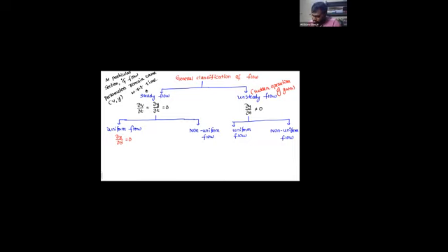And I can write in other words, if depths are the same, velocities are also going to be the same. So along the length of the channel, if the flow depth and velocity remain the same, then you are going to call it uniform flow. I have used this condition in the starting itself. Yes or no? And sir, where do you see this uniform flow condition, sir? So you have to say, where do you see the uniform flow condition?